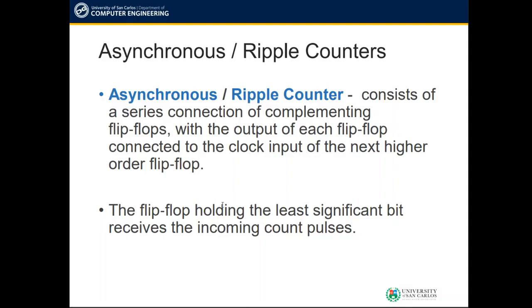The flip-flop holding the least significant bit receives the incoming count pulses. So this is the one that receives either the clock or the count pulses. Either you supply the clock pulses with the use of a push button or a switch, or you supply a clock source.